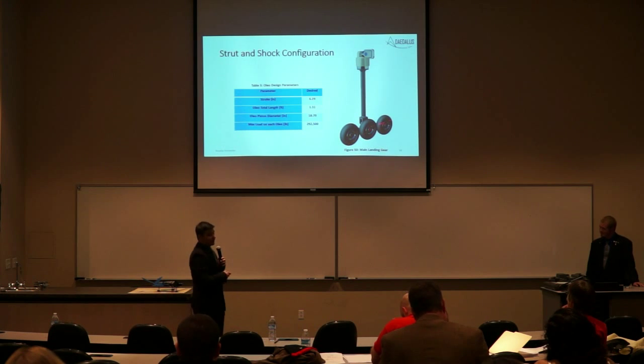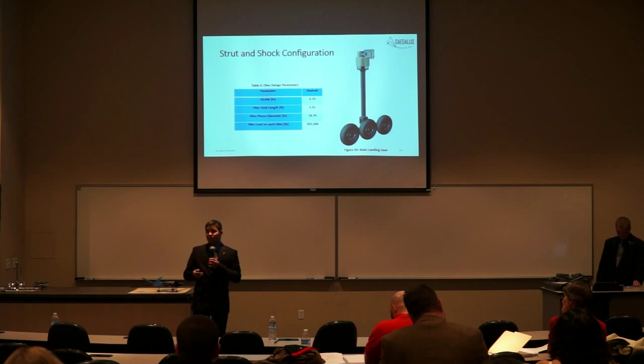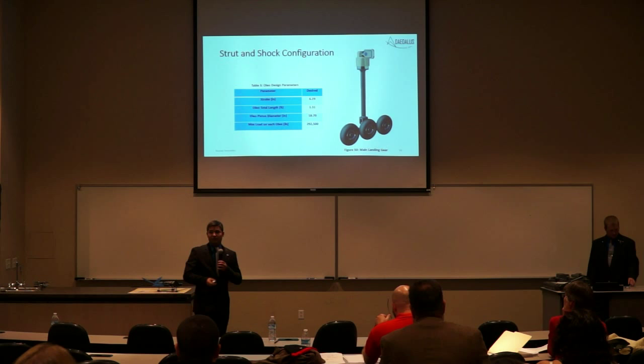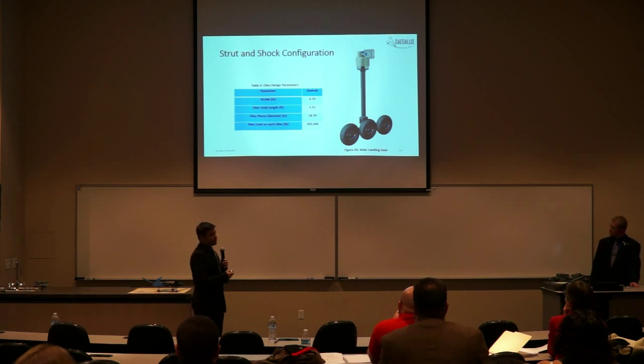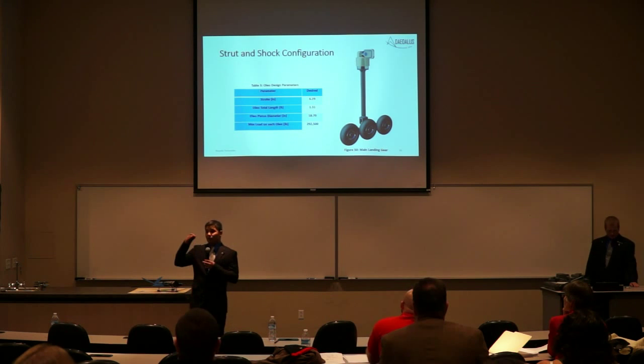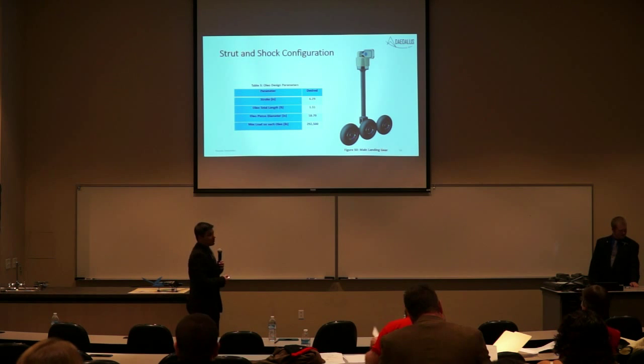As far as the main landing gear design, we went with an inline 3-wheel design. It is not a very common design, but due to volumetric constraints, mostly on the y-axis, because we have the engine right there on the wing and all the fuel tanks, it was difficult to place a conventional bogie landing gear. So we went for 3 inline, with smaller wheels as well, because our wing is so thin, and we didn't want any extra protrusions on the surfaces, to keep the stealth good. So we kept the wheels as small as possible.